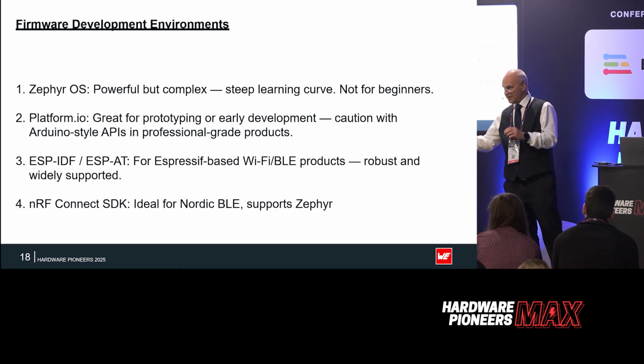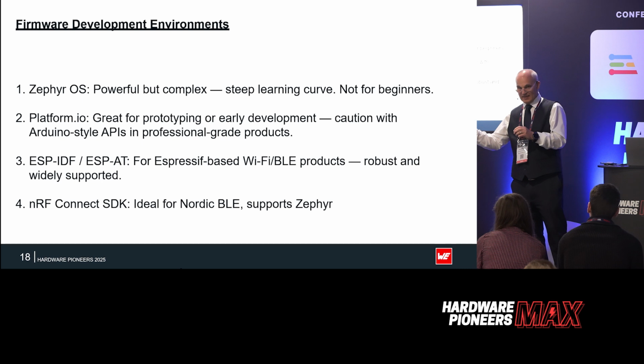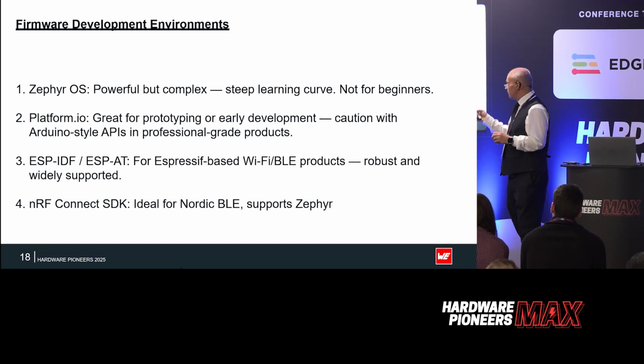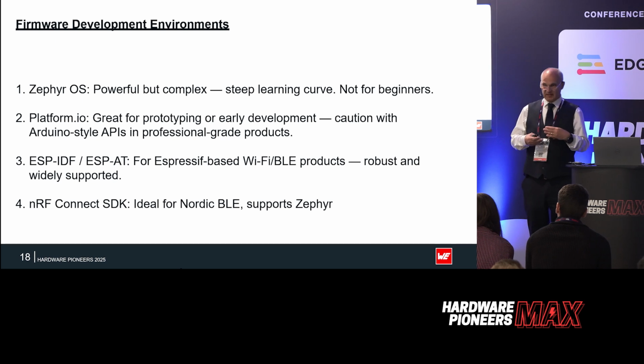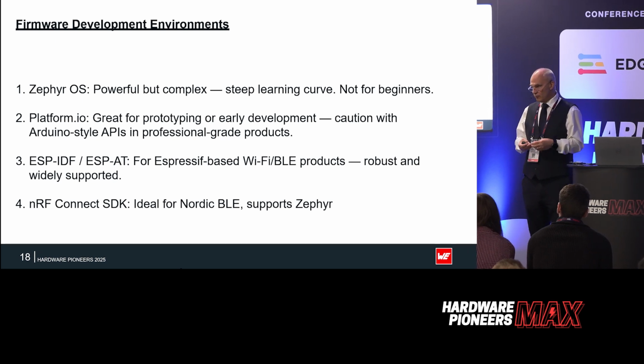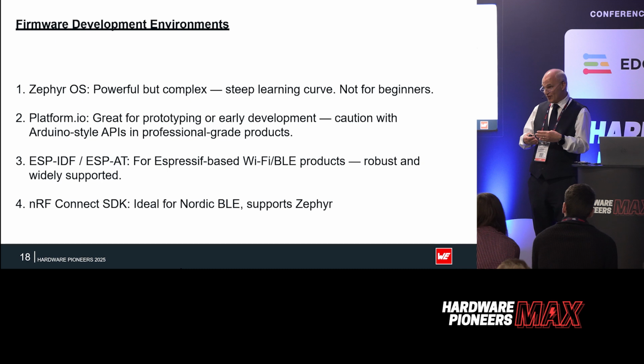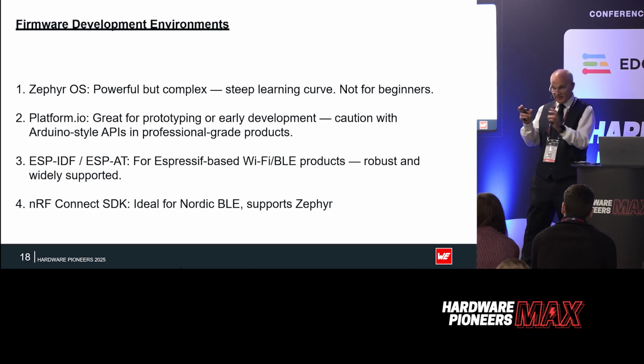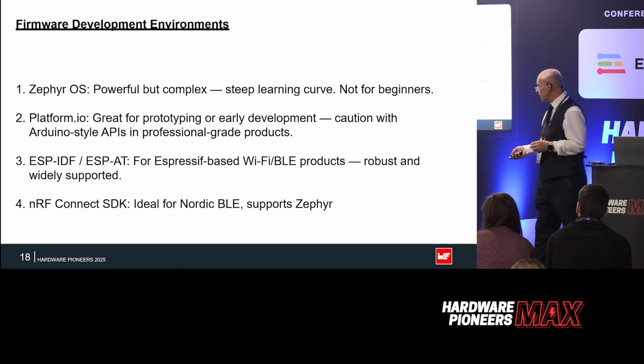We'll add a library into a project, and we'll leave it there. We don't tidy up. This gives someone the ability to hack that bit of firmware, so wherever possible, if you're not using a library or a little bit of code, you need to remove it.